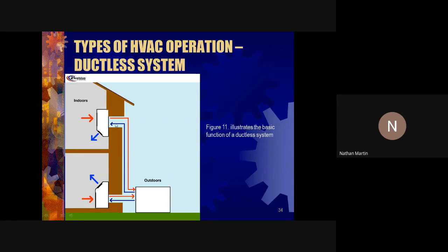Now, these are actually pipes that are also insulated. So what they'll do is run copper pipes from your evaporator units to your condenser unit outdoor, right? And then it will be insulated so as not to lose any efficiency. If the insulation is gone, it contributes in a negative way to the efficiency of the unit, right? Here, they're using a diagram showing it controlling two evaporators. So hence this is a larger type of compressor outdoor, right?